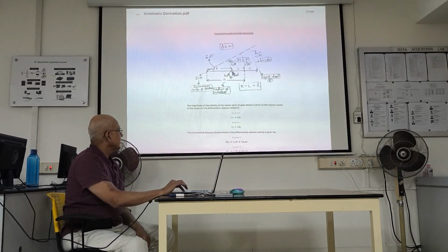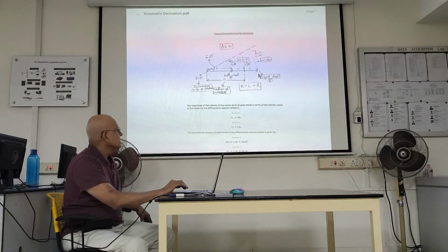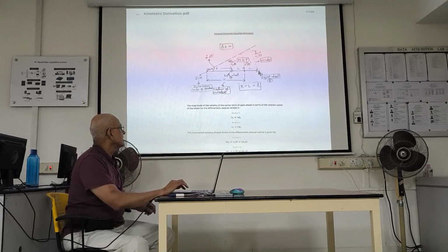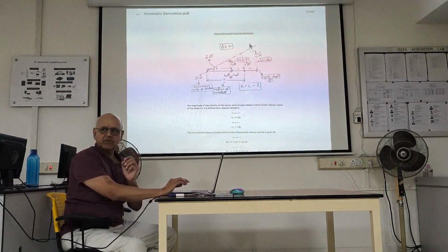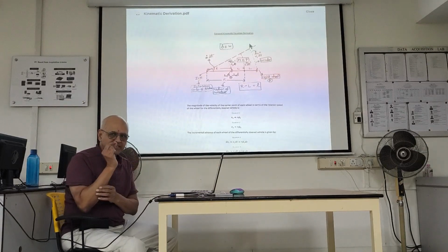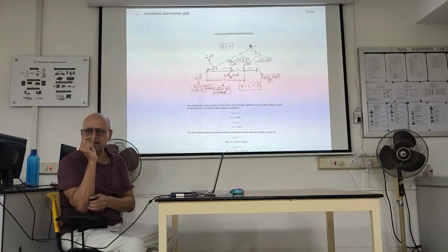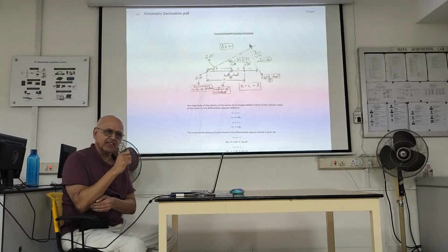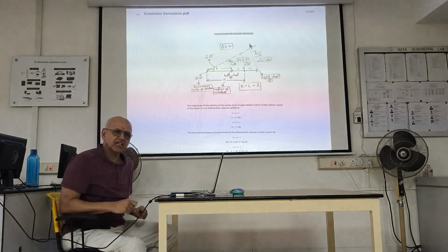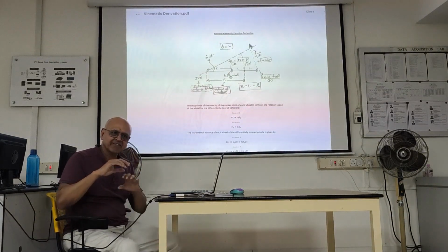I can't draw in 3D, so this is my crude sketch. What I'm showing you is the right wheel rolling out by a certain amount. I'm not using 1 second, because to be rigorous you have to use dt, from calculus, an incremental amount of time. The reason we have to do that is we have to allow for the fact that the velocity is changing. So calculus gives us this concept that we can assume that over dt, nothing is changing.